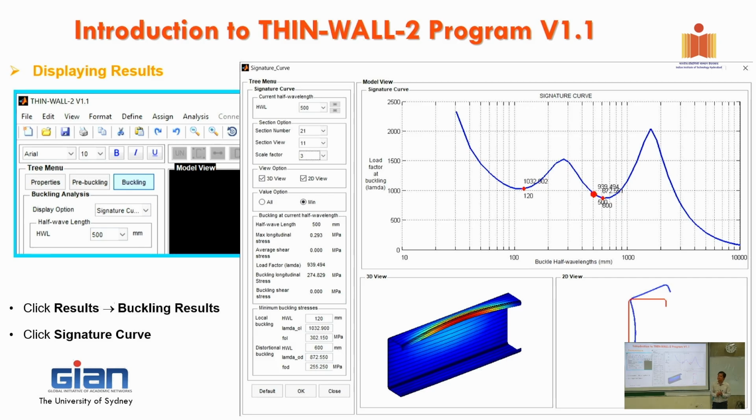bending that you apply. Everyone aware of the eigenvalue, right? So you put initial one, but you run it, you got a load factor. So it's actually the eigenvalue. So it gives you load factor. So now local buckling is about 1000 times. So it's 1000 something. It means that our buckling moment at local buckling is the initial one that you put, multiplied with that. So that is the MBL. That's the one you have, okay? So that's how you get it.